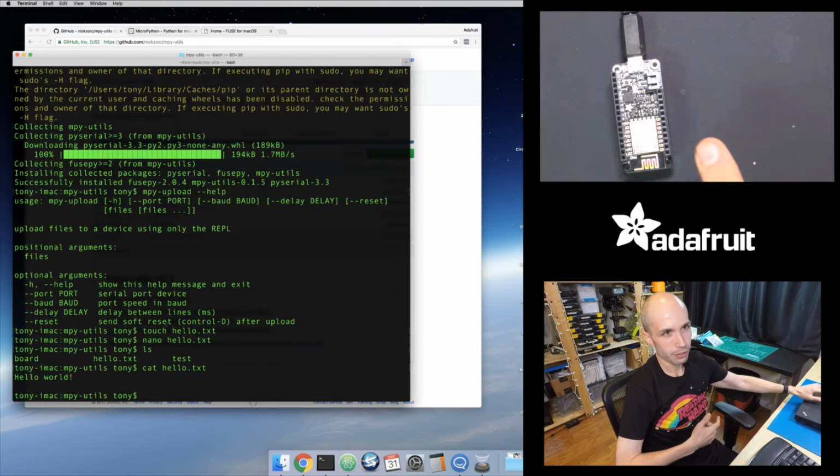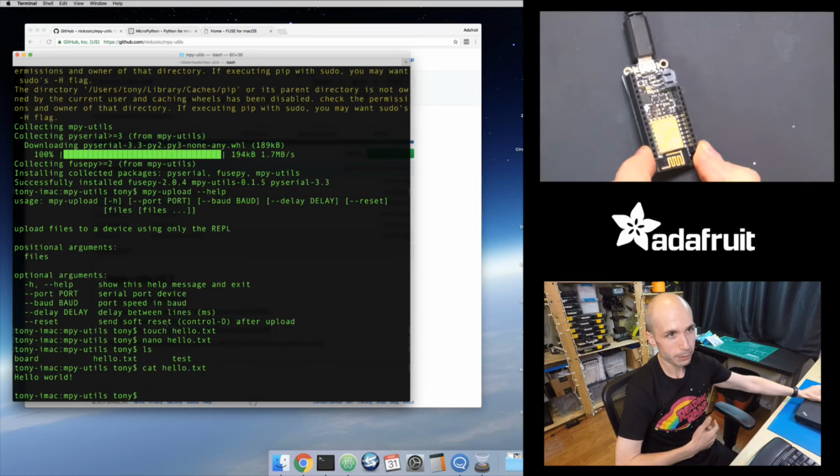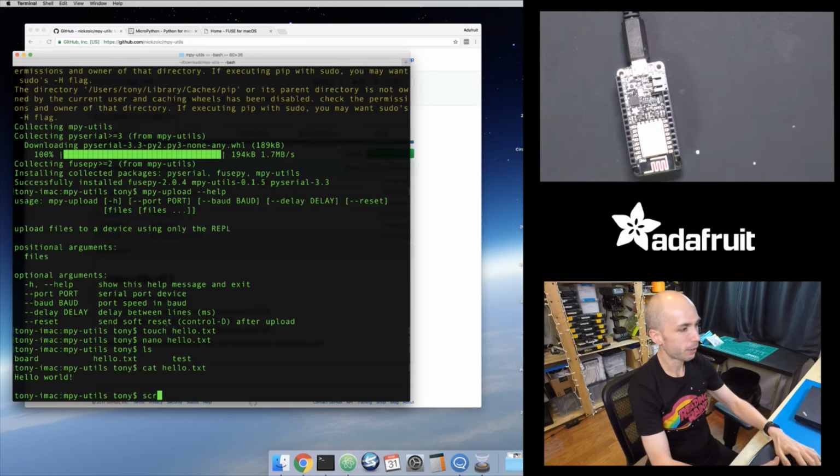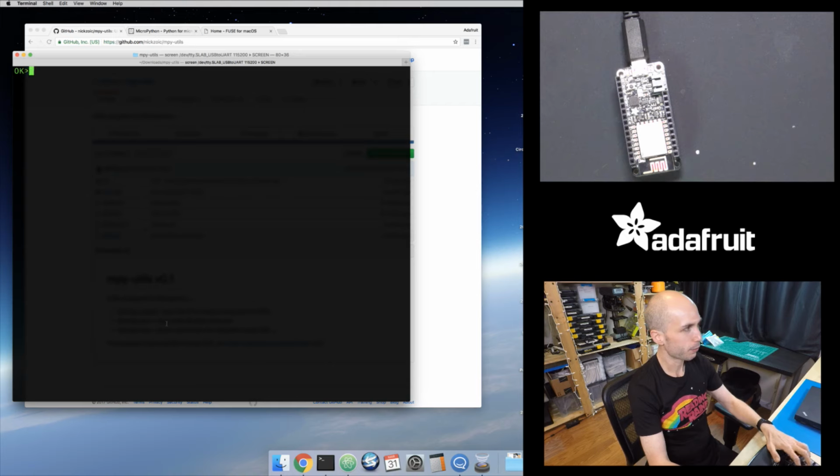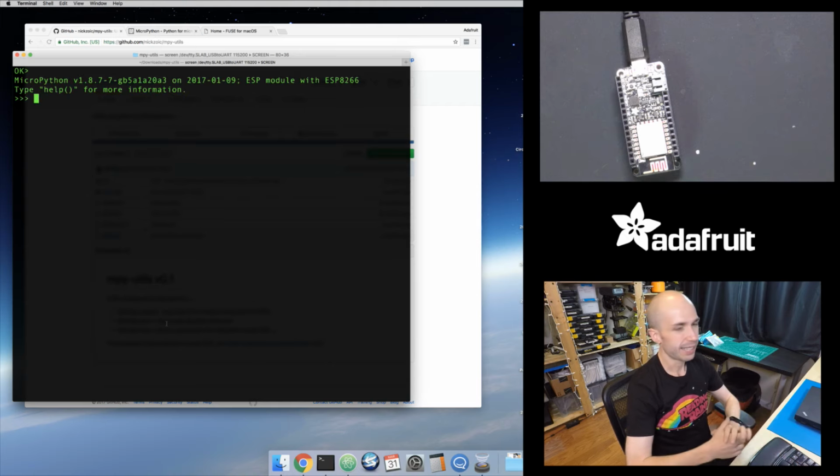And then to push this onto my MicroPython board, I've connected my board to my computer, and just to be sure it's connected, I'll connect to the serial REPL. So if I open the serial REPL for this board, it's the Silicon Labs USB to UART at 115200 baud. And I can see that if I press Control D and then Control B, I get my Python prompt. This is because when I was previously using the tool, it left the board in the raw REPL mode. So if you ever open up the REPL and you don't get anything, you're pressing enter or Control C and nothing's happening, try pressing Control D, D as in dog.